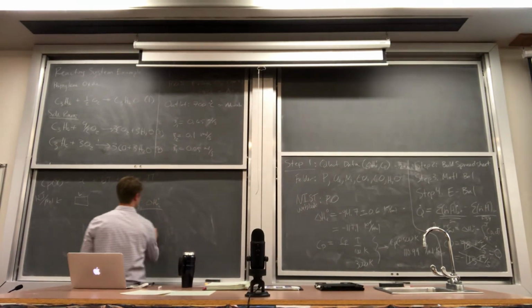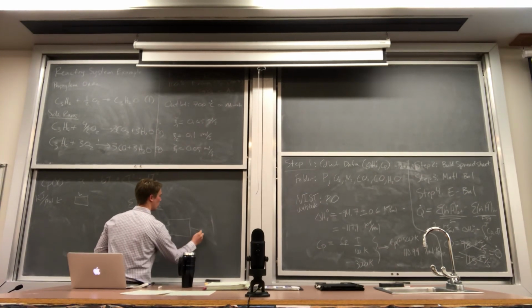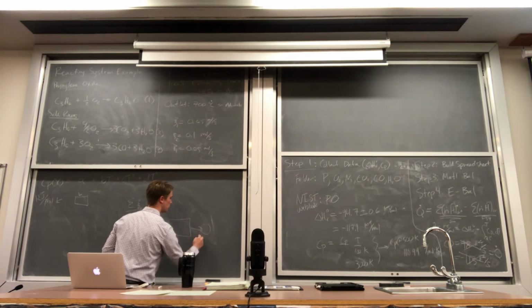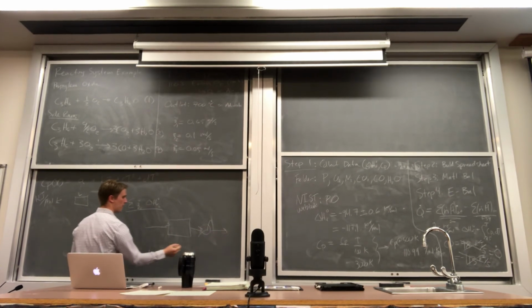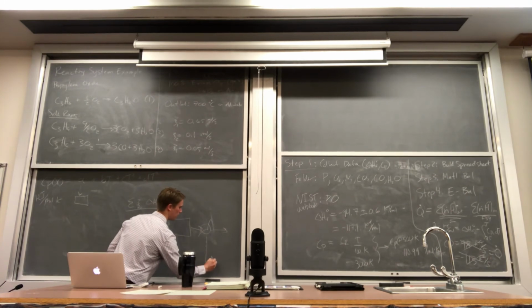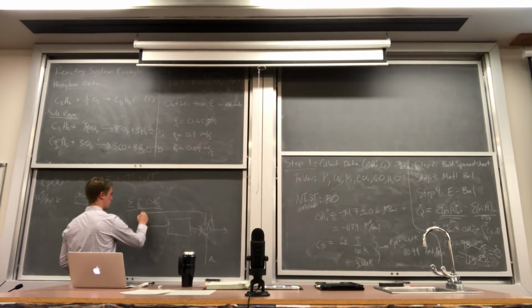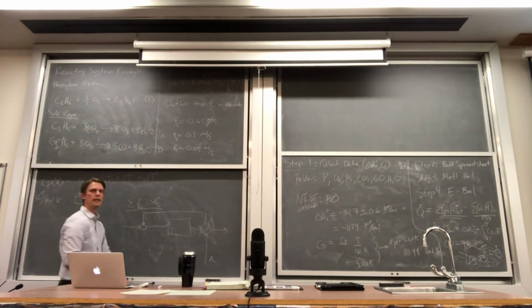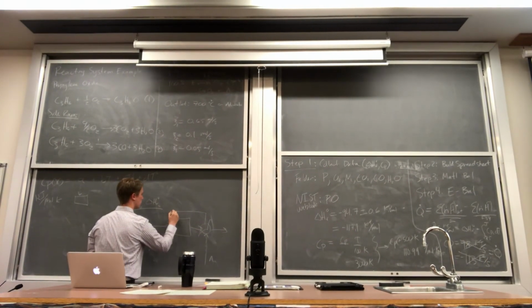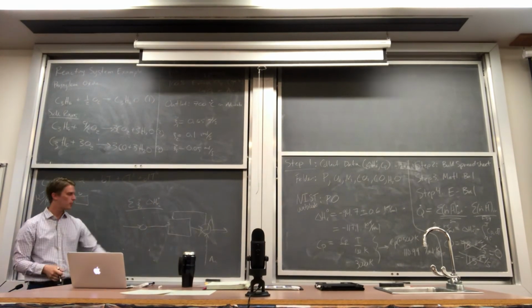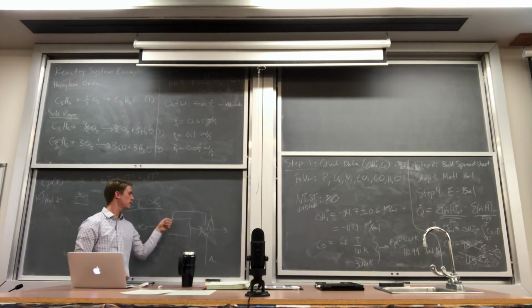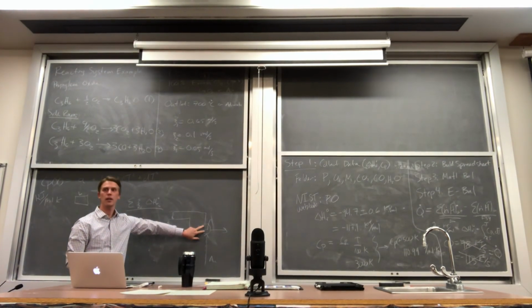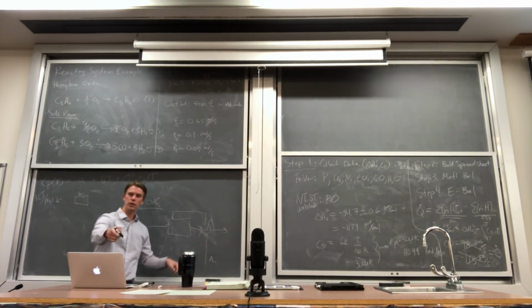So if we have a reaction coming into the system, what we would do in practice is have the airstream be cooling down the, well, we move it directly into the reactor. So we would preheat our airstream with the hot effluent gas and then send that into the process. That would be a smart decision to make in terms of energy efficiency. And if we were to do that, the energy balance on this heat exchanger would be from a gas phase that's hot to a gas phase that's cold. We could use our exact same spreadsheet.